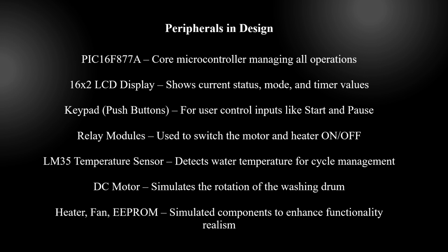And the peripherals in the design. The PIC16F877A is used as the core controller managing all system operations. The 16x2 LCD display displays system status, modes, and timer values. The keypad allows user inputs for selecting modes and starting or stopping cycles. Relay modules control simulated motor and heater operations.